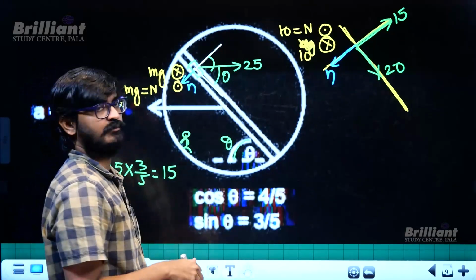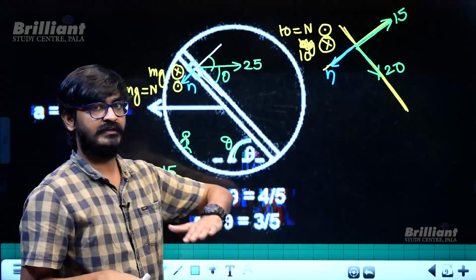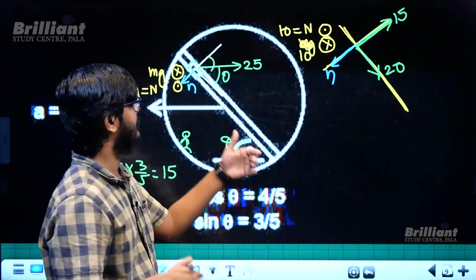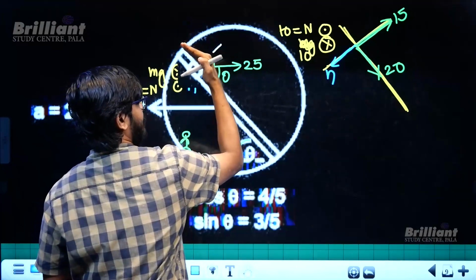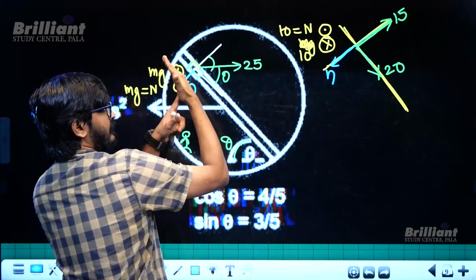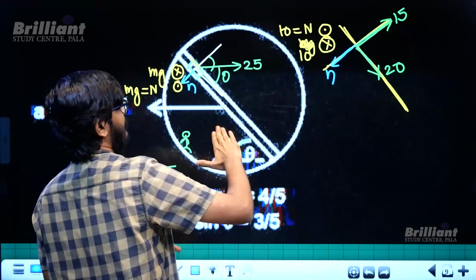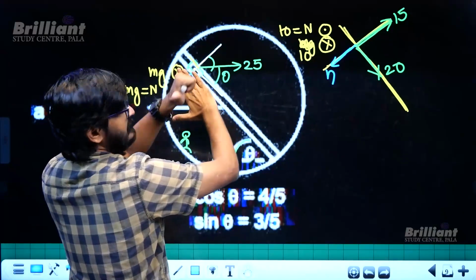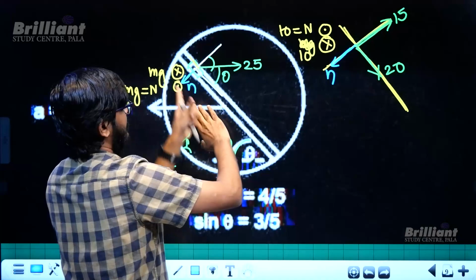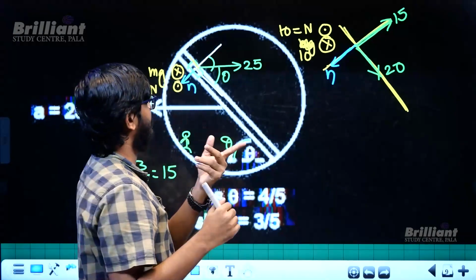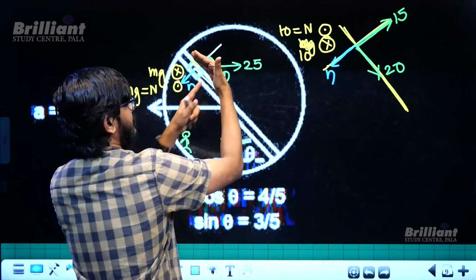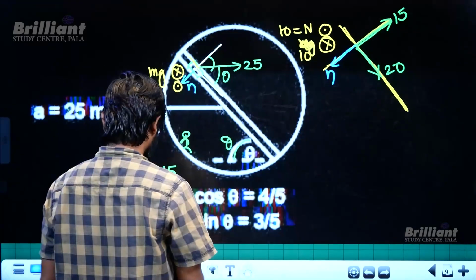Now there will be friction at both the places. There will be friction at the base, which is exerting the normal in the upward direction, and there will be friction at this surface also, right? It is trying to push the block this way, so there will be normal here, so friction will be in this direction. Now apart from that, this base is exerting mg in the upward direction, so there will be normal in this direction, so there will be friction in this direction. There will be two places where you will be getting friction, one because of the normal in this direction, one because of the normal in this direction. So there will be two kinds of frictions.